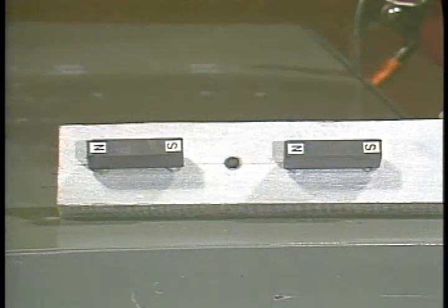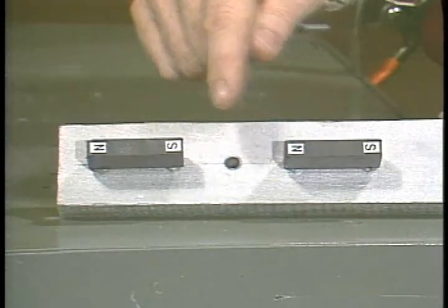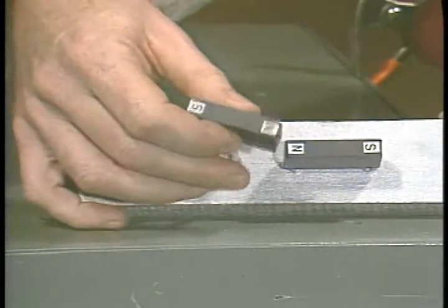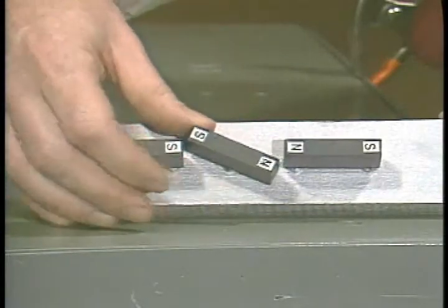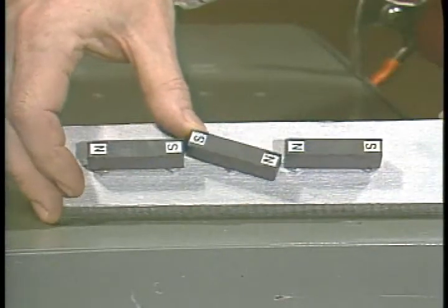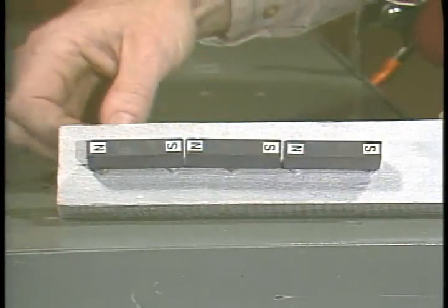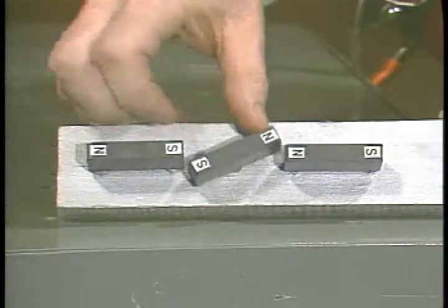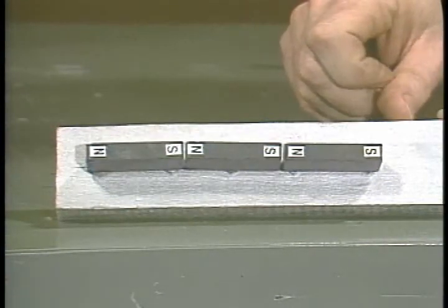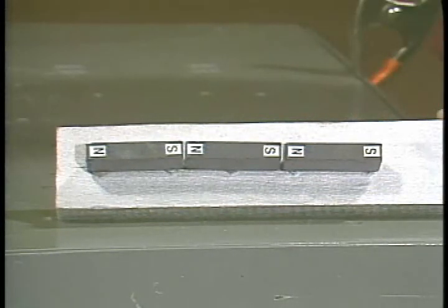We fix these 2 magnets in place with unlike poles pointed toward each other, north and south, so you can see how a motor exerts torque. These will be our stator magnets. When we pivot a 3rd magnet, a rotor, between them, the forces of the magnetic poles will turn it. And as it turns, the rotor is exerting torque. But once the rotor's poles have lined up north to south with the stator poles, it stops.